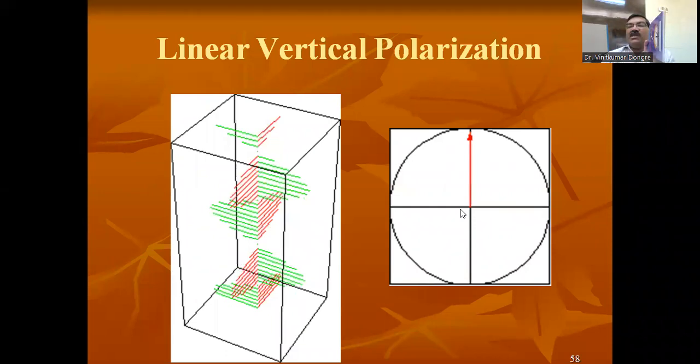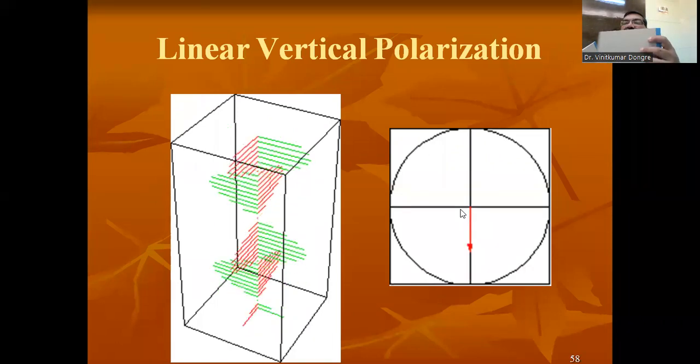If one is kept this way and one is kept that way, there will be a polarization mismatch, and optimum, maximum reception will not be there. Are you getting this? This is one antenna having horizontal polarization, and this is another antenna having horizontal polarization. If both antennas are horizontally aligned, they will receive the maximum radiation. One is transmitting, one is receiving.